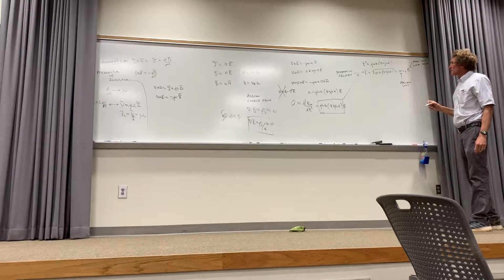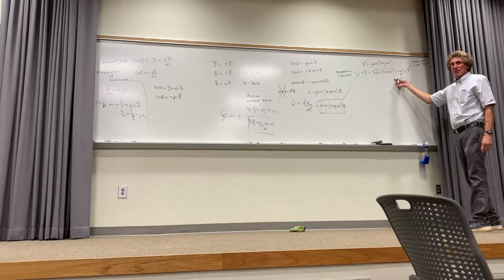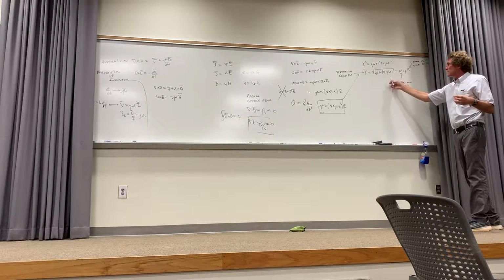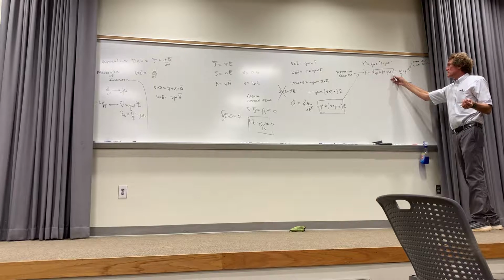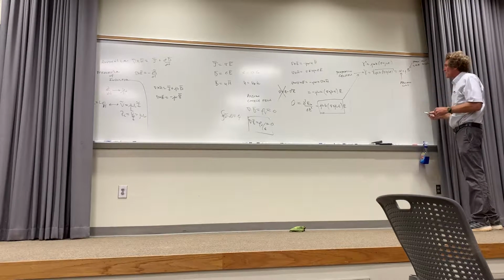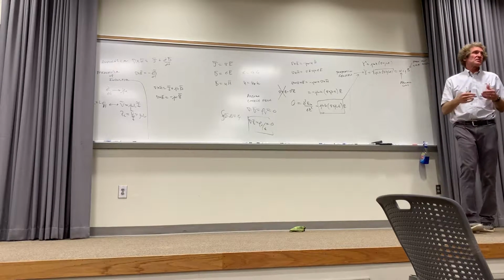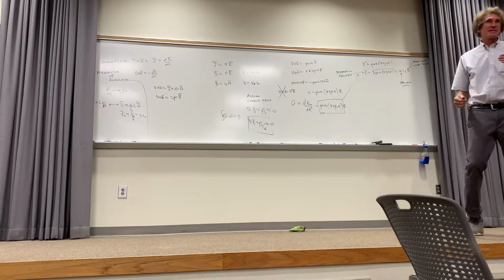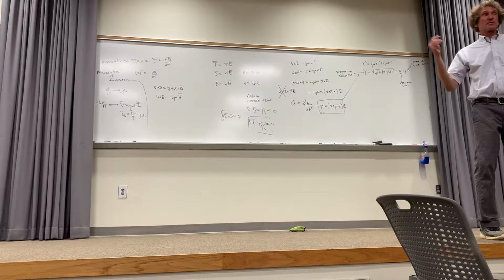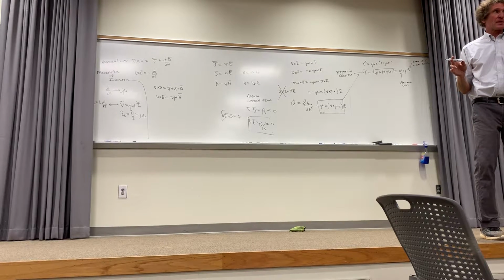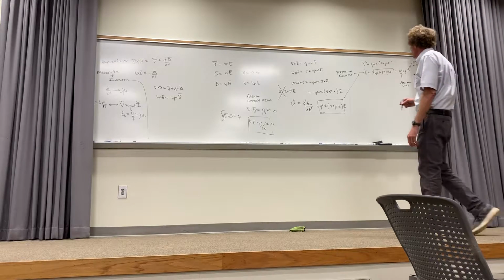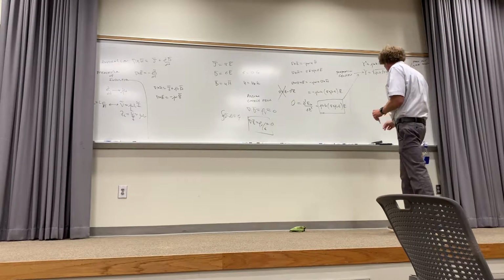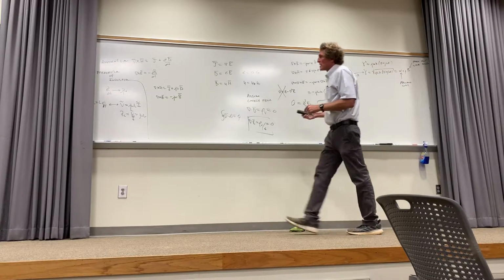Now, the attenuation coefficient here only has a non-zero value if sigma is non-zero, or, and you will see with complex permittivity, if the complex permittivity has a loss component. In other words, alpha means the energy is being dissipated. Now, if there's nothing to dissipate energy, there's obviously alpha 0. Because this has to do with the decay of the amplitude of waves. And I'll show you that in a second. So let me take it from here and move back here and get rid of all this.